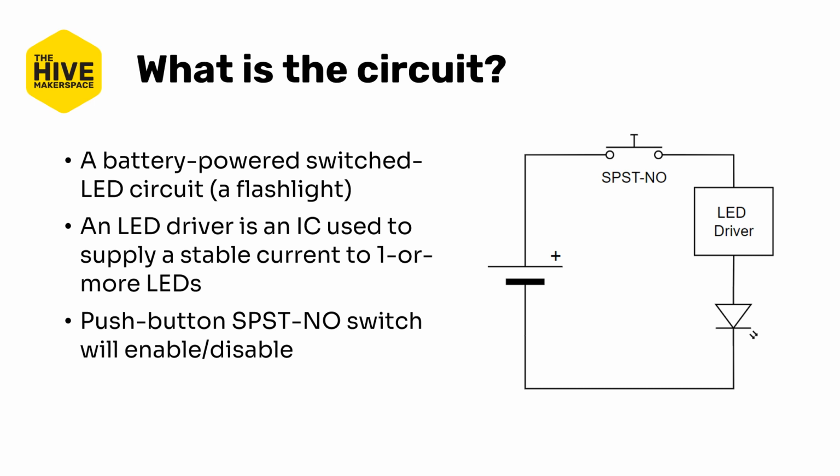We'll use a simple push-button tactile switch in a single pole, single throw, normally open configuration that will turn on and off the circuit, or really enable and disable the LED driver. And the power will come from a single coin cell battery.